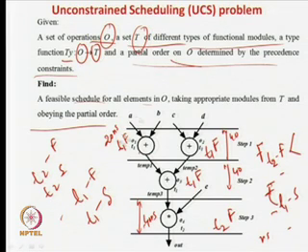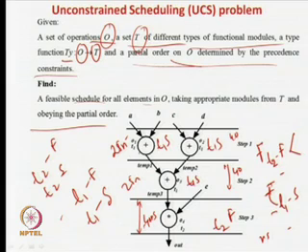So, let me try the other way. I use T2 fast, but now I put T1 slow here, T1 slow here, and here also T1 slow. So, I will get the answer in 25 nanoseconds here, and here also in 25 nanoseconds. But still I have to wait for another 40 nanoseconds. So, even if I get the result in 25 nanoseconds, it does not make any difference for the adders, because the time step is 40 nanoseconds, so I have to wait.